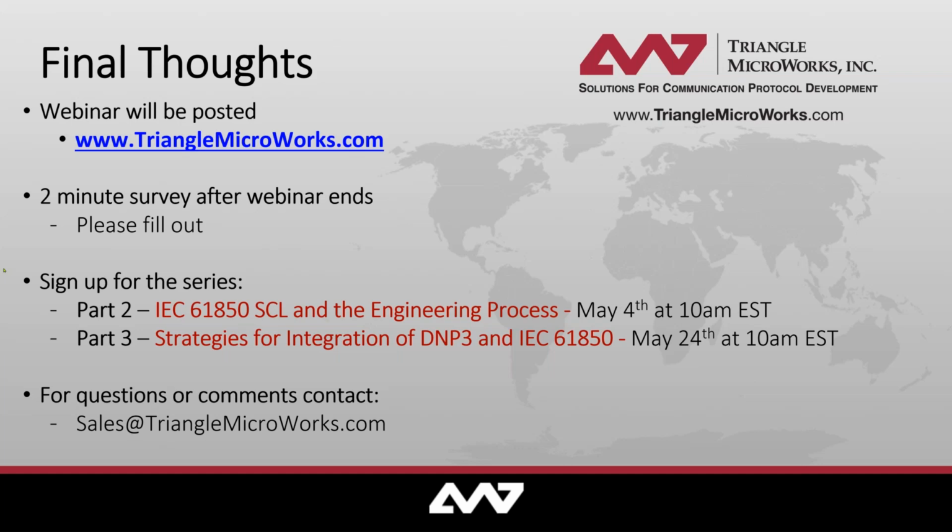Okay. Sorry, I missed the first part of the question because I was typing in an answer to another question. So MMS is not publisher subscriber. MMS is client server, and there is always an association between one client and one server. Yes. But you could create multiple report control blocks which share the same data set, in which case you could have multiple. I suppose the limit is defined by the specific device that you're working with, in terms of the number of report control blocks that it would support.